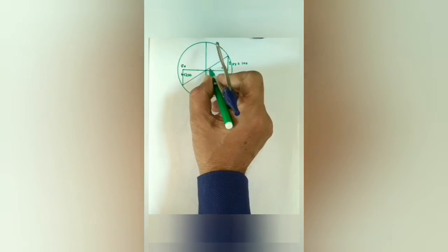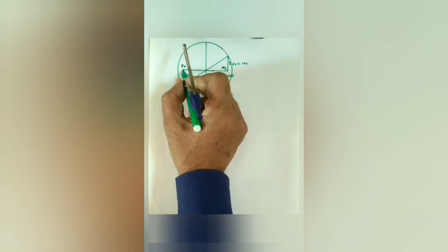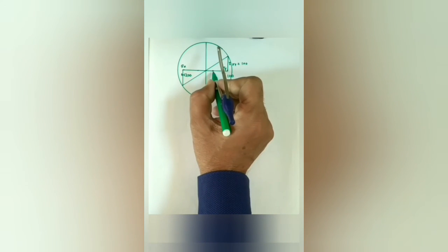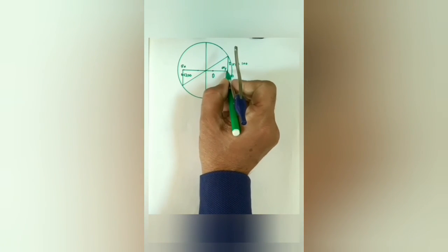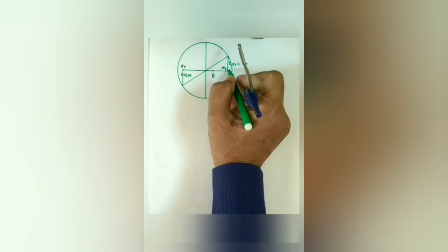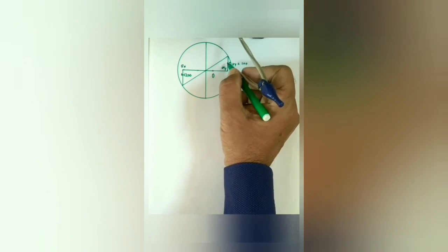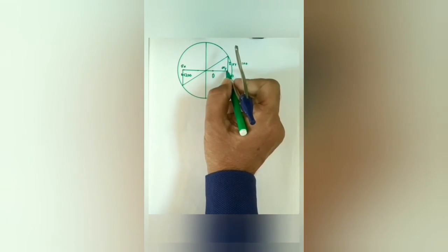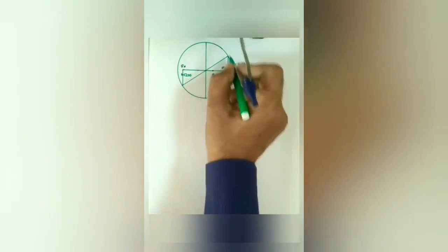We draw sigma x, since it is negative, in the opposite direction, that is minus x direction, 200 MPa, and sigma y 100 in the positive x direction, and then tau xy 100 like this, and we draw a circle from the center of sigma y and sigma x.